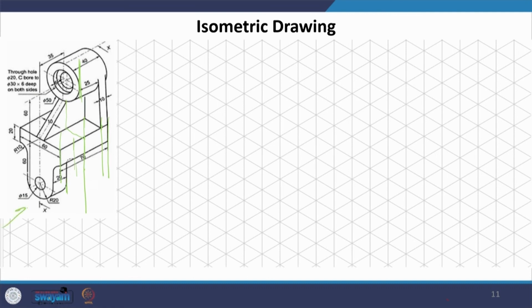So, we can draw the front elevation from this side, because this is where the curves are going to come. We see the curves, and we look at the heights at which the centers of these circles are coming from each other. We draw the front elevation, draw these lines in the plan and arrive at the plan and elevation simultaneously. In the previous examples which I was taking, we were looking at drawing one object first, just the front elevation or just the plan, but in complicated objects you will have to simultaneously arrive at all the drawings. So, I will stop here today.